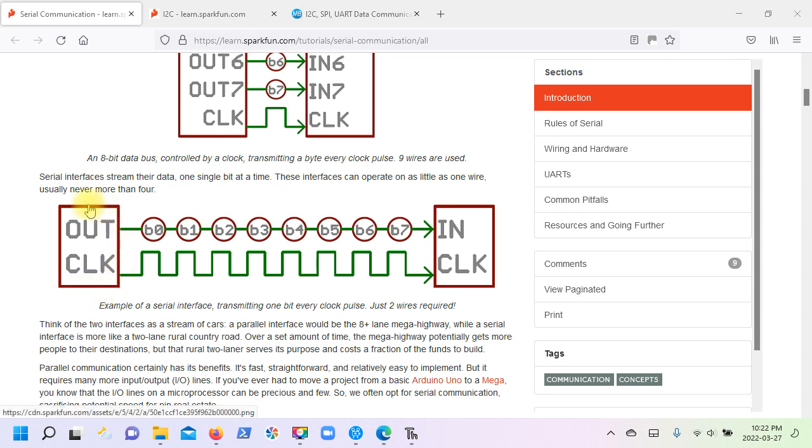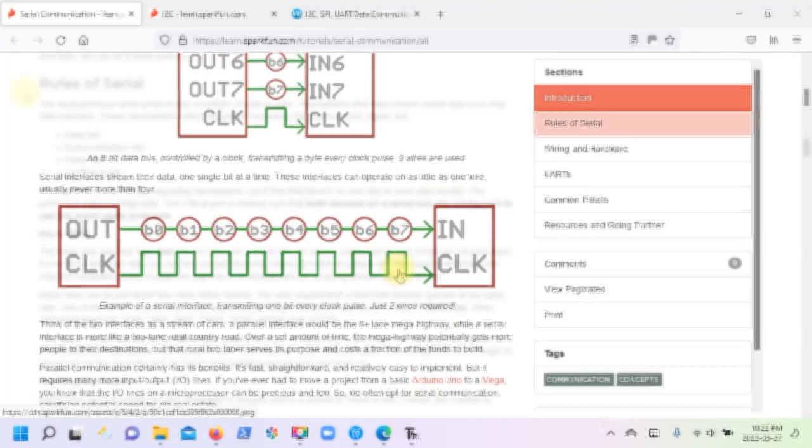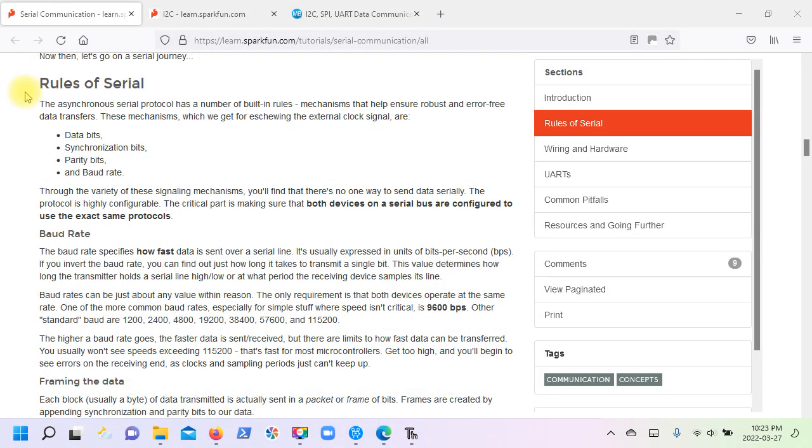When we look at serial communication, we have a device, such as the Raspberry Pi Pico, talking to another device serially. Those data bits have to be sent one after another, synchronized to a clock pulse. So you can see in serial communications, you need a lot less data lines. In our book, we're going to be talking about serial communications.